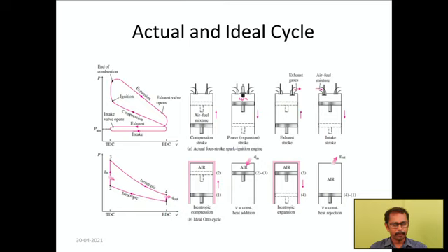In the compression stroke, the air fuel mixture already available in the combustion chamber will be compressed to high pressure so that the temperature and the pressure are increased. During this compression stroke, both the valves will be closed.